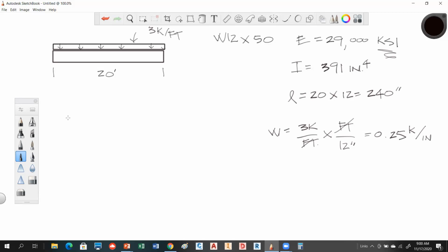That says delta, which is your deflection amount, is equal to 5 times w, w is your loading rate, times L to the 4th, divided by 384. That's a constant, so that's also a unitless constant. So that has no units involved. Then E times I, there's your beam stiffness.